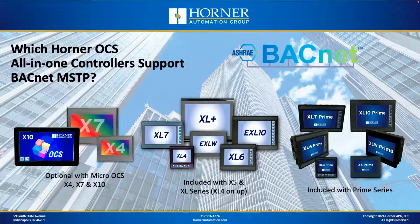And really, this applies to both BACnet MSTP as well as BACnet over Ethernet or BACnet IP. So first of all, the Prime series and all the XL series from the XL4 on up, as well as the X5, those products all have it built in and standard from the factory. So if you're using those devices, your controller just has BACnet, both IP and MSTP, built in.